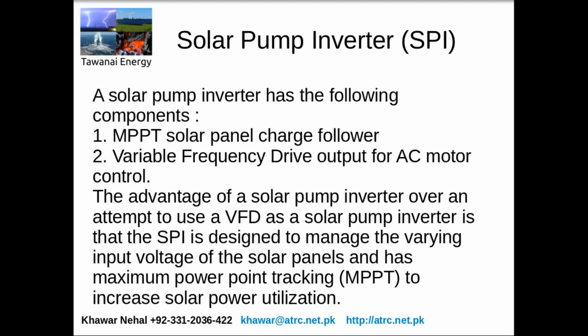A solar pump inverter is similar to a VFD, but it has extra components in it. One is that it has an MPPT, solar panel charge controller. That means it can find and track the maximum power point of a solar panel, so that will give it more efficiency if a solar panel is connected to this. Then it has a VFD component, which is the one that actually uses the DC bus.